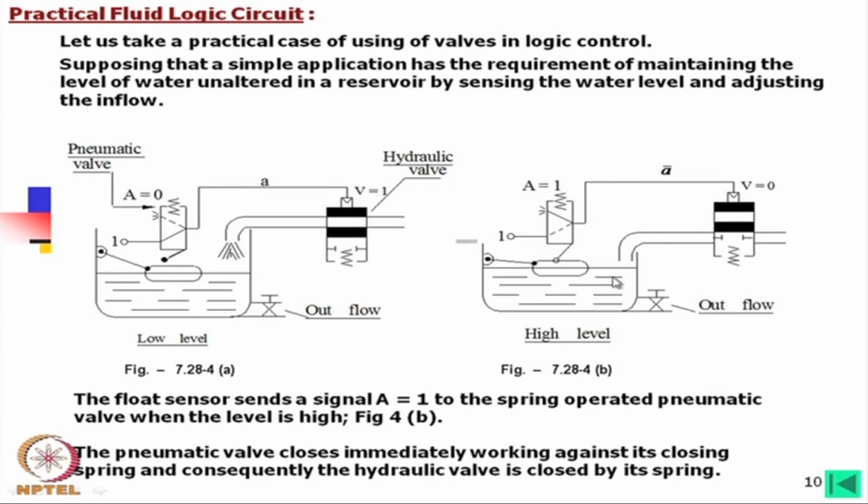If the water level comes down and it immediately starts operating, then again it will go up, and sometimes that is not desired. When the water is coming down, it has to go down to a certain low level, and only then will this valve start. So, it needs another delay switch which is not shown here. It is only shown that when it is filled, then this valve is stopped.